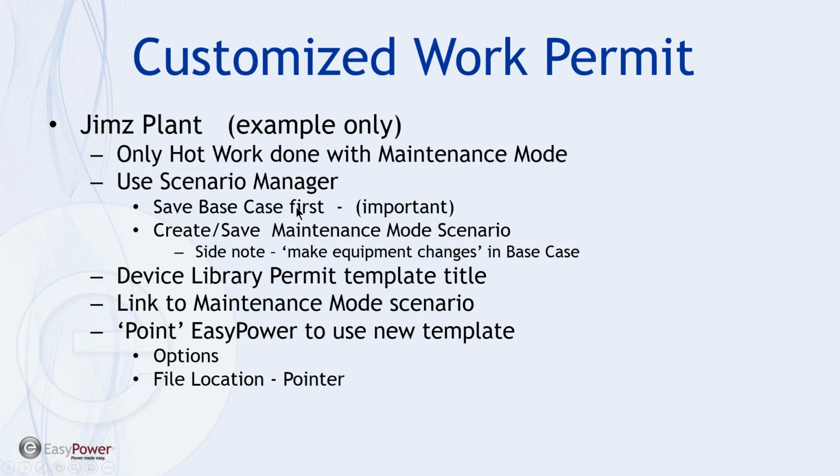For those of you that don't use it as much as you would like, it's probably important to point out that before you start creating scenarios, you save the base case, and I'll try to point this out when we get into the tools. The situation there is, if I've saved the base case as a document or as a case in the Scenario Manager, then I can create additional scenarios using that base case.